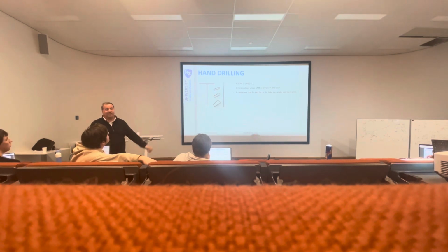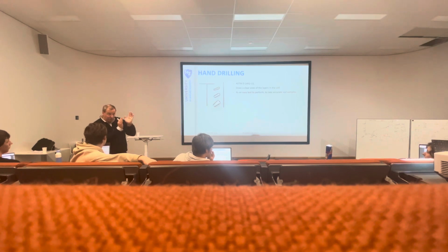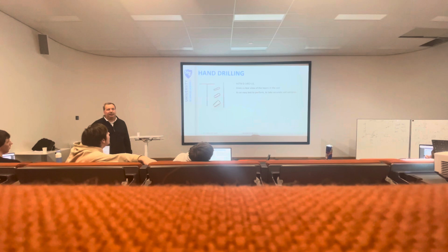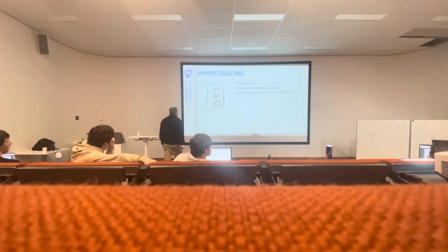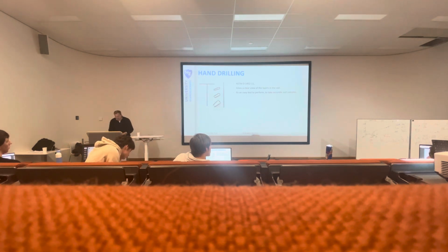That's why this type of test we're not going to do anymore that much. It's all mechanical now. You push into the soil, and based on the pushback that you get, the friction, it's all being measured, and we can determine what type of soil is there. In the good old days, it was still take the soil samples out by hand drilling, even when it was raining.